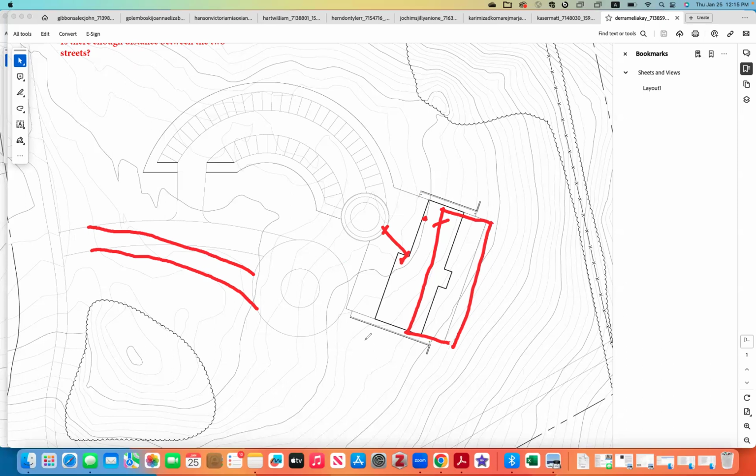There is a benefit of moving just a tad. Reason being, we're in a pretty steep area here. Shift everything down. Honestly, if you move everything down by one contour, it will be much easier later. The thing with that is that the road right now is right outside of the 50-foot drip line of the bottom left vegetation. From there to that vegetation is just 50 feet. I just need to turn this curve.